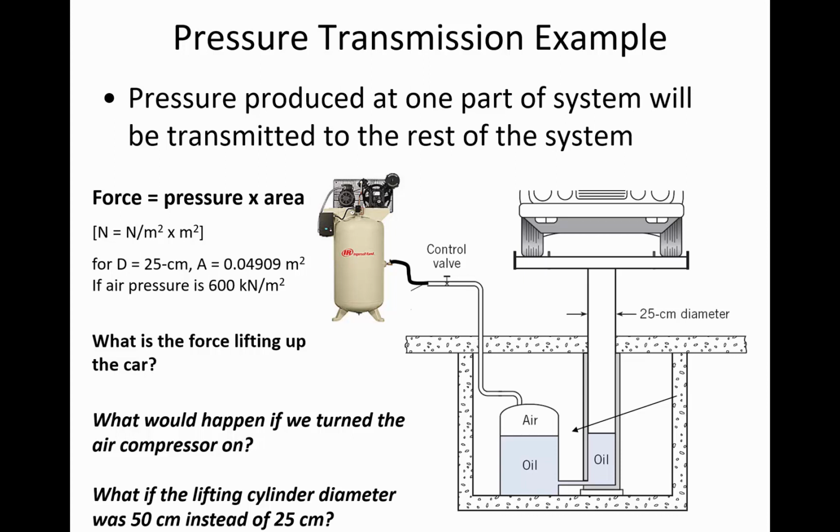And area is pi d squared divided by 4. Dalton's got it right. So he's saying that it's going to be 4 times as much force. And that's right, because if you double the diameter, then that's 4 times as much area, because pi d squared divided by 4. So if you go through the numbers here, back to the example,